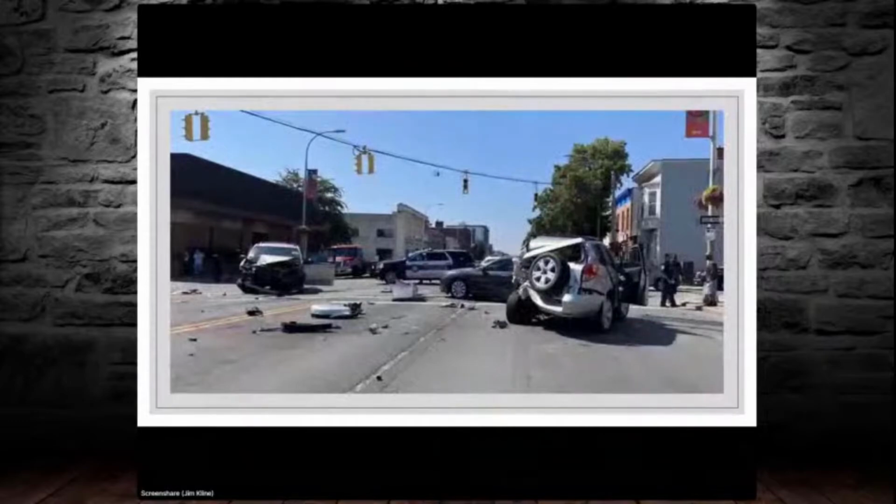You've got to be careful about this one because care must be taken as to where and how we write the code so that we do not inadvertently change the traffic pattern when the button is pushed. The traffic flow sequence can't abruptly change and cause the street that has traffic flow to change from green to instantaneous red. The code design must allow the normal sequence to proceed until it arrives at the delayed green section, and then it can hold traffic for an additional amount of time for the pedestrian to safely cross.